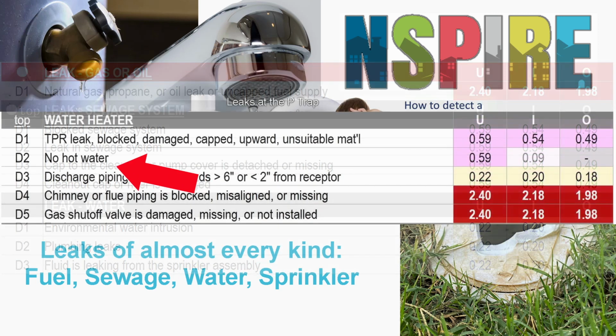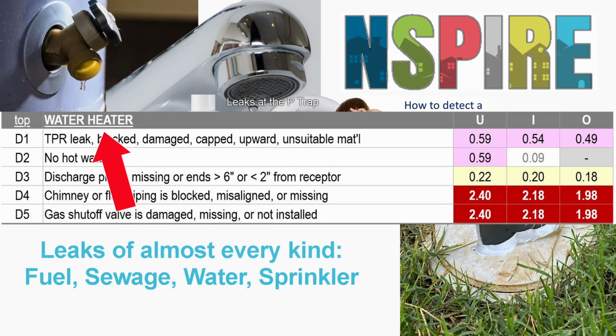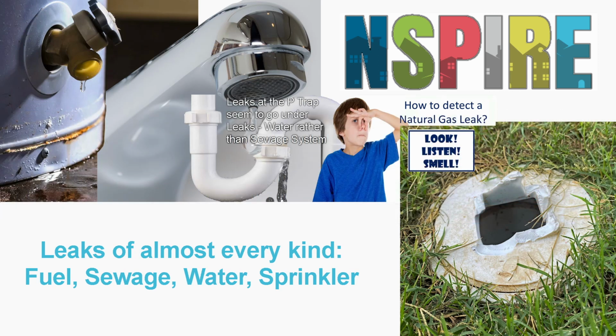There's a separate water heater deficiency that can include leaks at the pressure relief valve, and for some reason, this deficiency is worth nearly as much as the other 3 types of leaks combined. Please look for that under the water heater standard. Of course, those are all freshwater leaks. We also have sewer plumbing leaks, which have a higher scoring value yet.